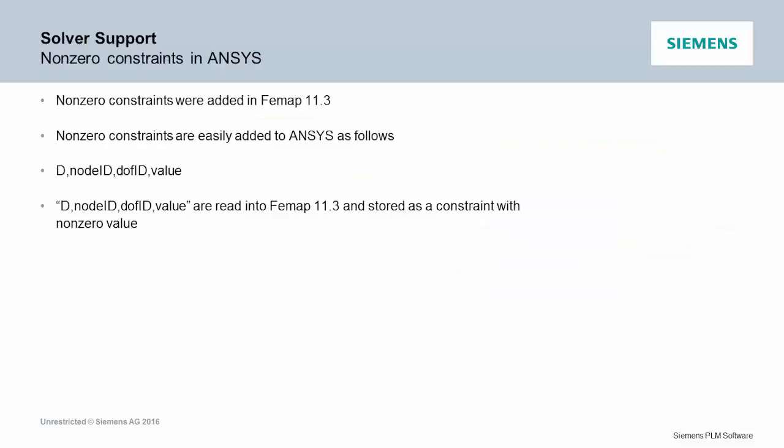Same thing with the non-zero constraints we did in Nastran with the SPC. He did that also for ANSYS and Abaqus. So if those exist in your model, they'll get written out correctly so that they'll run the same in ANSYS or Abaqus. And he also did the CLAS. I already told you about the CLAS and the C-bush to ground. All those are taken care of.